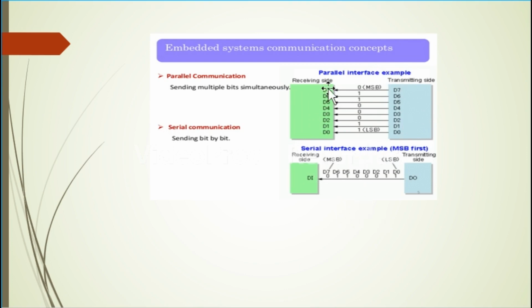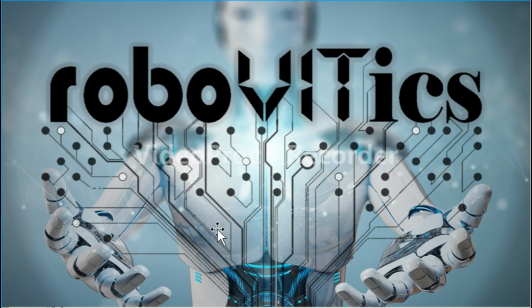But the fact that these are transferred not in a sequence but parallelly makes it more prone to distortions. So the data can end up becoming distorted on the receiving side. Therefore, parallel communication is usually preferred for shorter distances as compared to serial. And that explains serial and parallel transmissions.